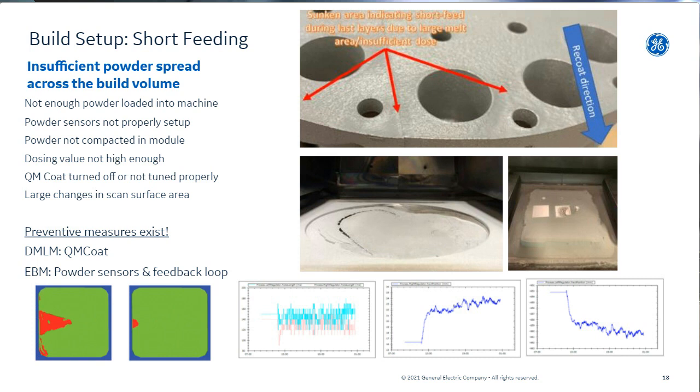The bottom left one there, I don't know if anyone's seen our tree that we did for the zoo. This was one of the trials where we ran out of powder. We were skimping by with some powder that we had, thought we had enough, pretty close. We turned off the powder sensors because we knew we would be close. Or rather, the powder sensors were still active, but the build would not stop if it sensed zero powder. So zero powder pulses were happening. We came in the morning, you open the window, you look in there, and you see this huge void, lack of powder. Essentially, it is attempting to spread powder and none is being spread, so it lowers the table, scans again, and you get further and further out of focus.